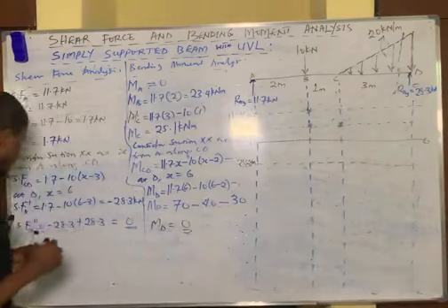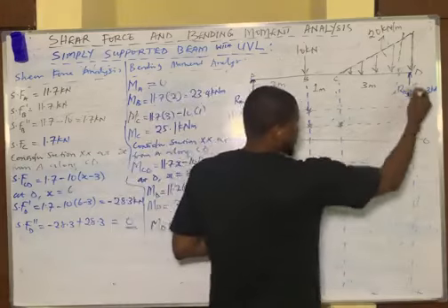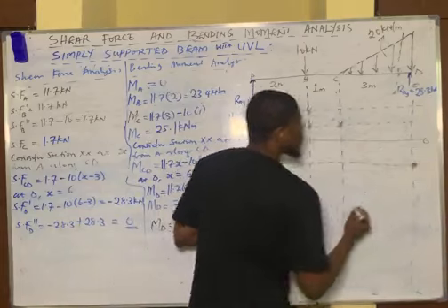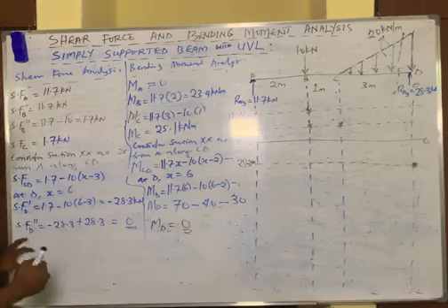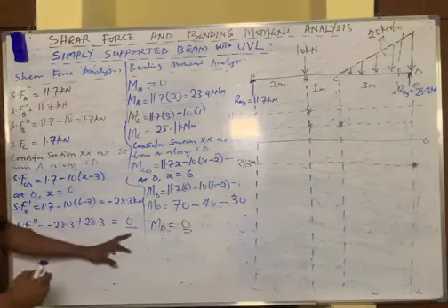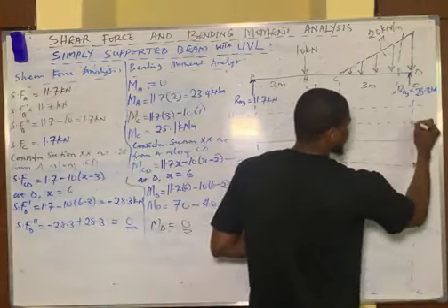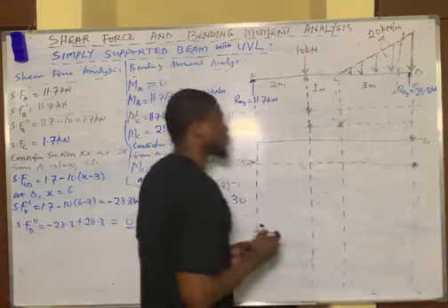Okay, so shear force at D initially is negative 28.3. So this is line D. So initially you have it here, negative 28.3. And finally shear force at D is simply 0. These are the 0 mark, right? So you mark an asterisk here and you have this.